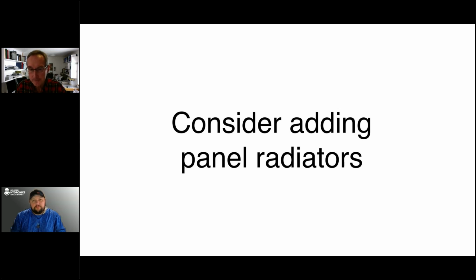Yeah. And your units have controls that can do that automatically. It's not that they need to have an external controller to do that. Correct. The WV and the AV unit both have that as an option in a control. Yeah, it's all built in. So you just select the high water temperature and the low point water temperature, and then we have 15 different curves in between on how aggressively you want to achieve those temperatures.